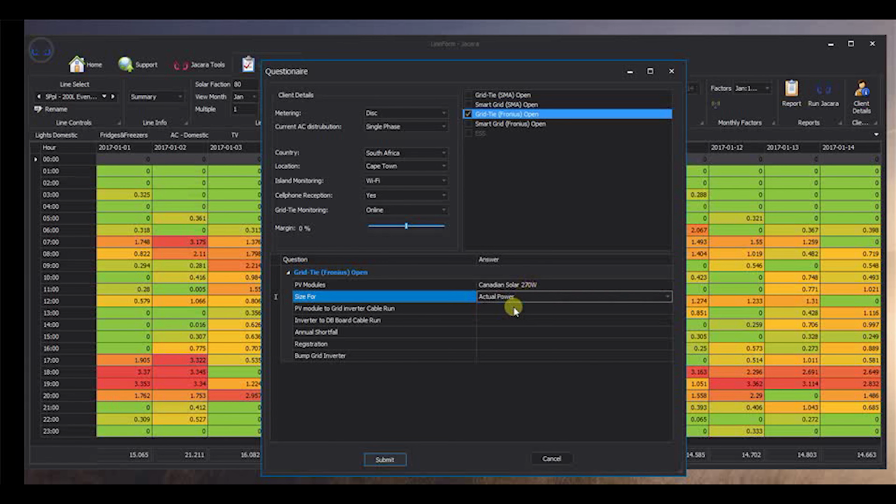It gives me a little bit more flexibility when you design on roofs that face east and west and different directions. Very often you would get a smaller inverter than you would have expected, because the combined rating of the panels is slightly less than the rated power.